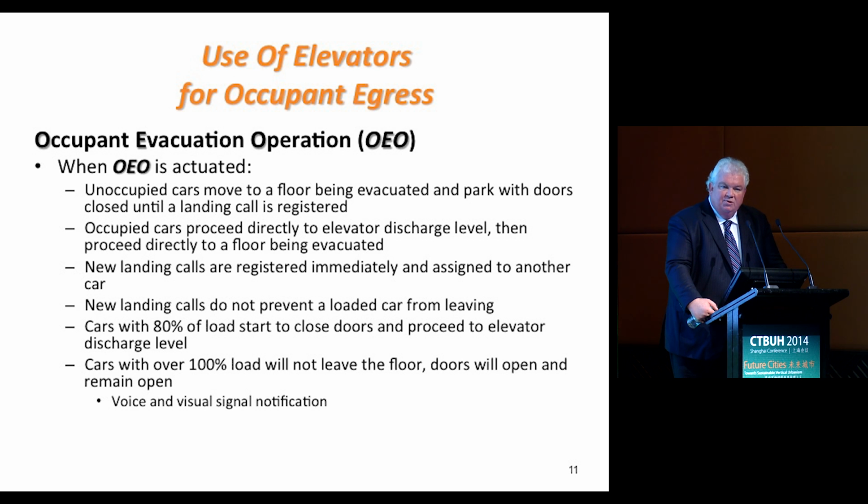Cars that are 80% loaded would be instructed to leave the floor, close the doors, and proceed to the discharge level. But if somehow they do become overloaded, they will not leave, and you'll get a message telling people to get off the car. The doors will stay open until you're back down to the 80% level.